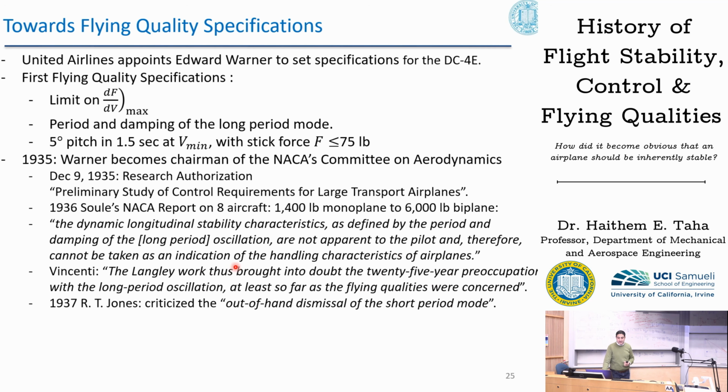R.T. Jones, in the very next year, criticized, on the other hand, the dismissal of the short period mode. So you guys keep talking about long period, long period, long period. What about the short period mode? They ignored it on the basis that it's too fast, so the pilot most likely will not feel it in flight. It will not be observed, so they just ignored it.